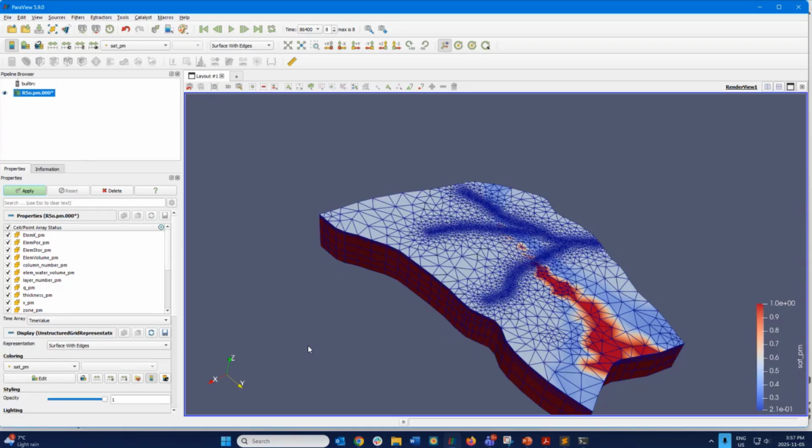So you can have a 5-meter resolution for a catchment scale model. You can have a 5-centimeter resolution for a catchment scale model. But those two models are going to take very different times to run through a simulation. So it's impossible to really answer that question clearly. All I can say is that the resolution of the model is entirely up to you, but there is obviously going to be a limit on what you can do, just based on the computational resources that you have available to you.